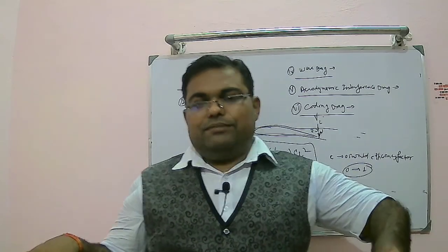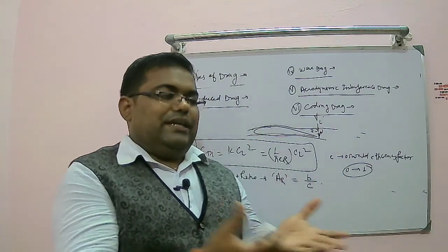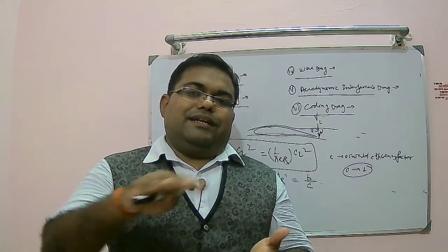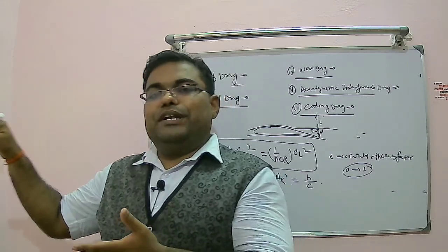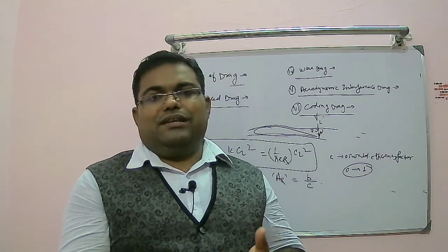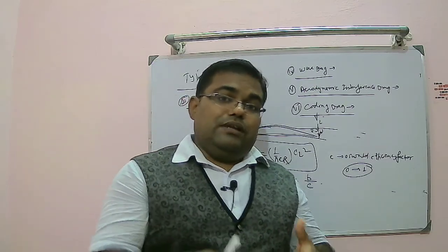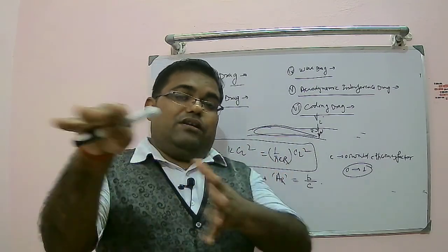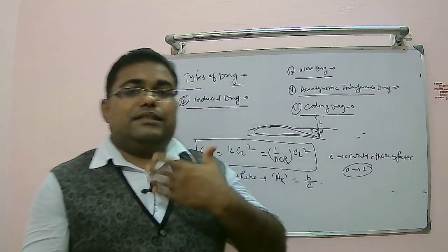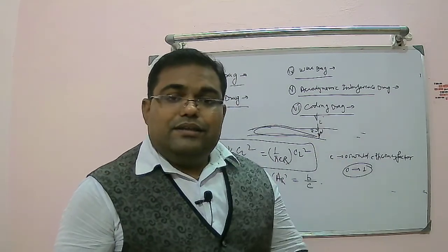The aircraft engine will be subject to a very high temperature environment. To cool that, we take atmospheric air and pass it over the various components of the aircraft, and that also contributes to the drag, because air has viscosity, and viscosity contributes to skin friction drag. The drag due to the movement of free air over various components or compartments of the aircraft is known as cooling drag.